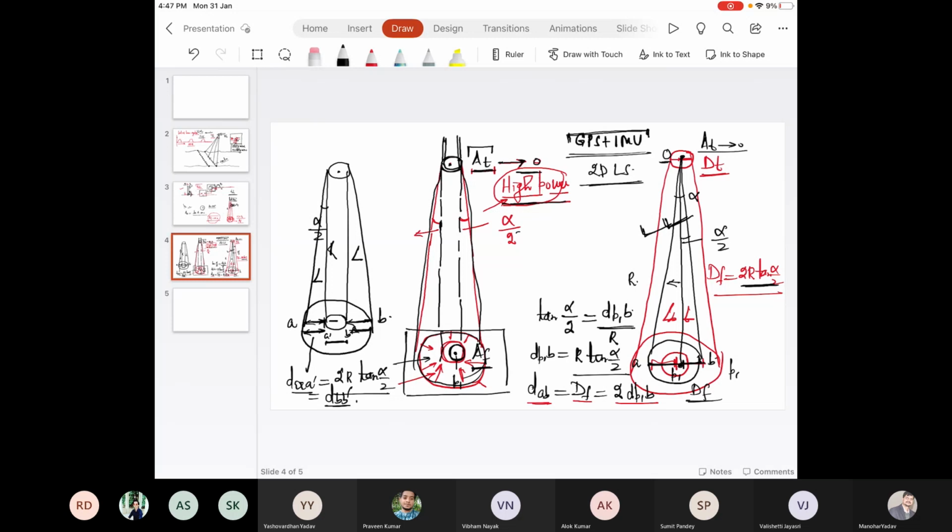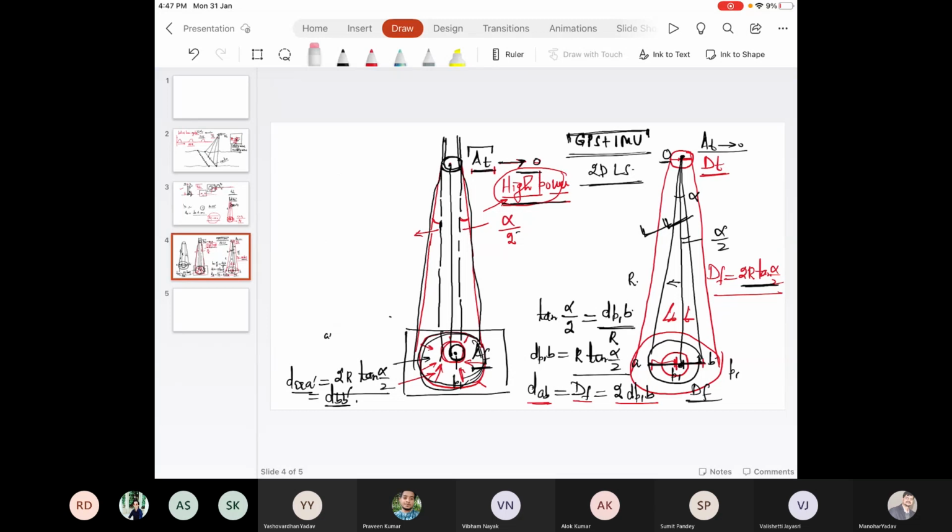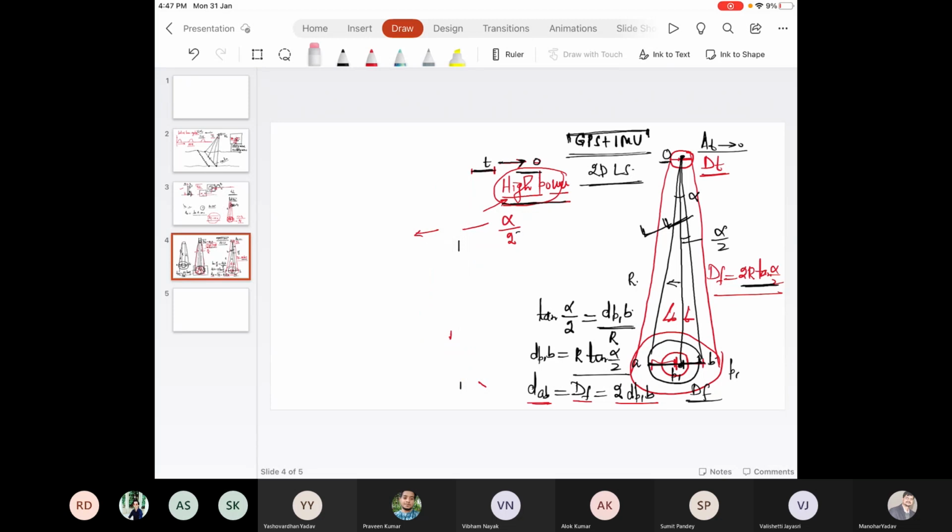Even though this is a part of further lectures, I would like to highlight it. If you want to analyze the actual footprint with respect to the range measured by the sensor system, say the target point is P1 and the range is measured, there will be distortion at an off-nadir location.